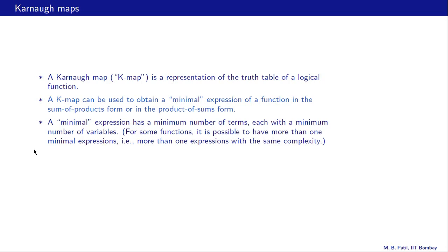The question that we should ask ourselves is, what is a minimal expression? Here is the answer. A minimal expression has a minimum number of terms, and each term has a minimum number of variables. So that is what minimal means. The next question that arises is whether each logical function has a unique minimal expression or not.